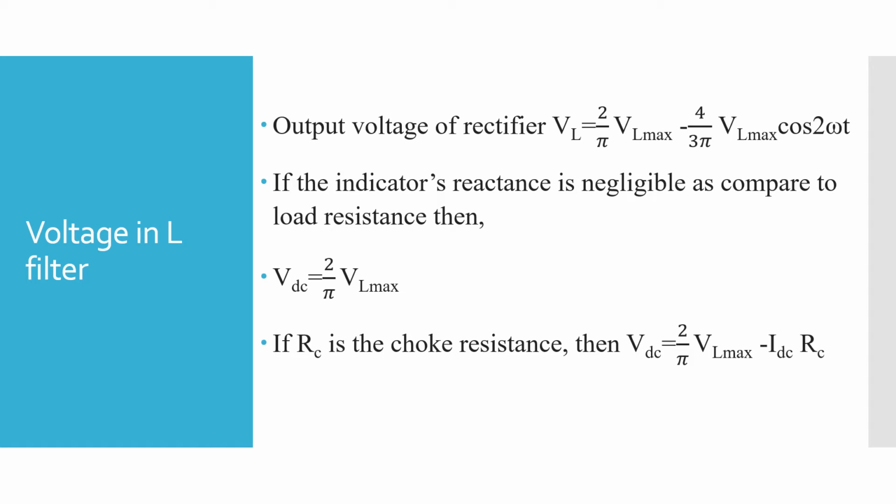If the inductor's reactance is negligible compared to the load resistance, then VDC will simply be 2/π VL max, since this whole term disappears.